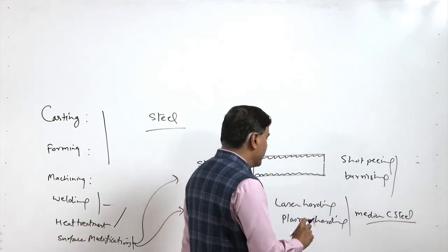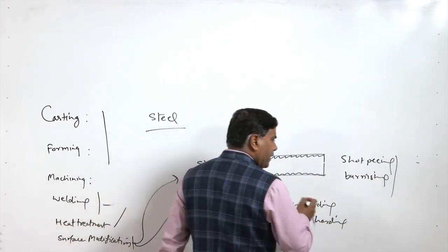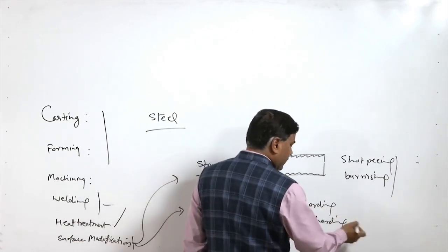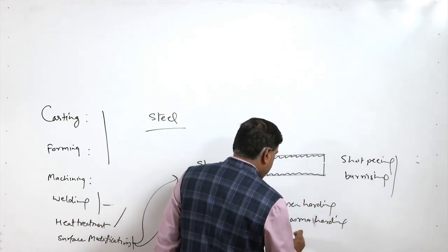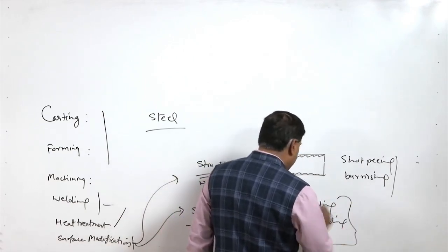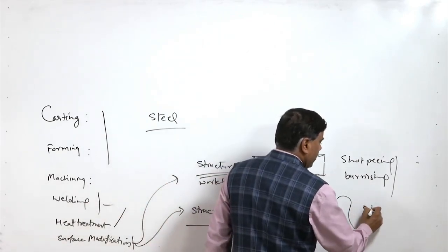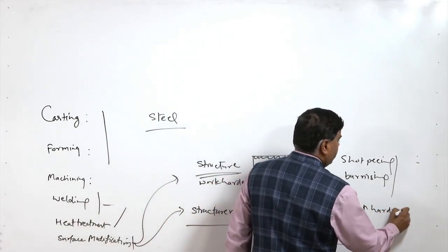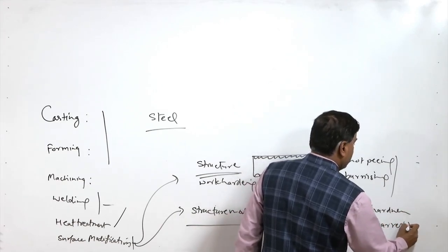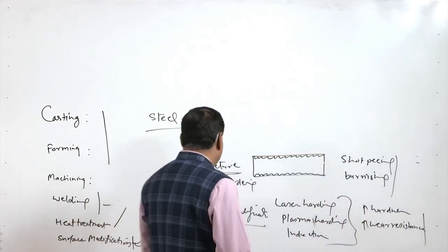The beam is directed, so it gets austenitized, and then sometimes self quenching or external quenching can be used for the hardening purpose. Induction hardening is also one of the examples where just the structure is modified. The purpose of all these processes is to increase the hardness of the steel surface, so that wear resistance can be enhanced.